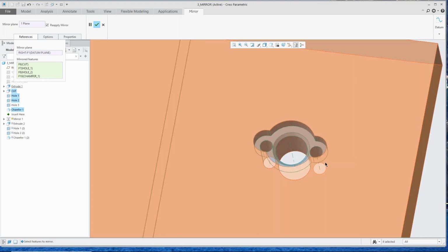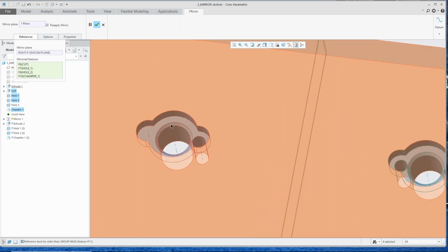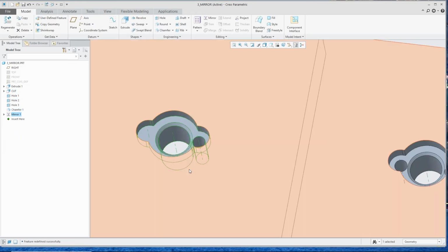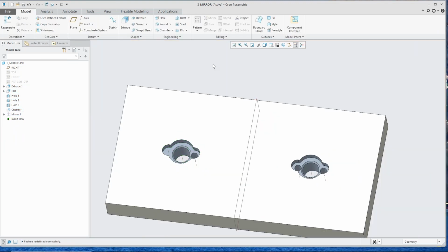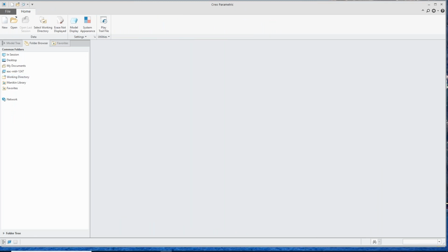And what it does is it can grab those intersected closed areas and use those as a sketch region. So that is really kind of useful. Instead of creating multiple sketches, you can create a single really complex sketch with lots of overlapping geometry, and then use the overlap sections, as long as they're closed, to create the geometry you want.